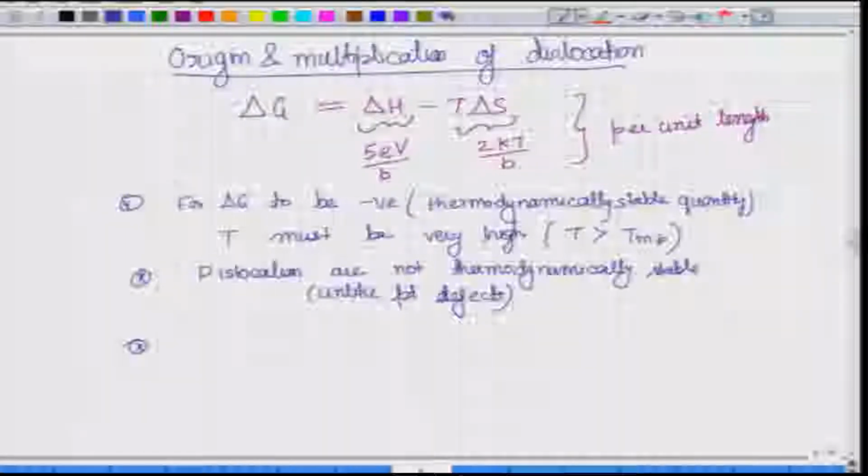I mean, if you anneal for however much time, and if you try to grow a single crystal, still we talk about the presence of dislocations, something of the order of 10 to the power 10 per meter square. So, why is there dislocation? And that is because no matter how you have created your material, if it is of even a decent amount of size, there will be enough stresses inside it that dislocations will get generated.